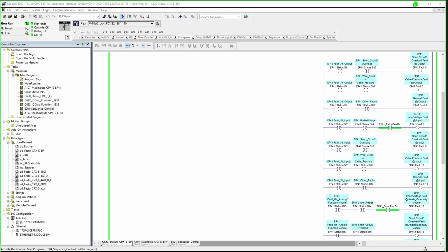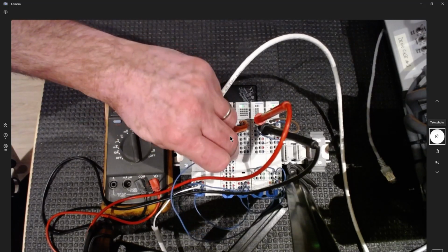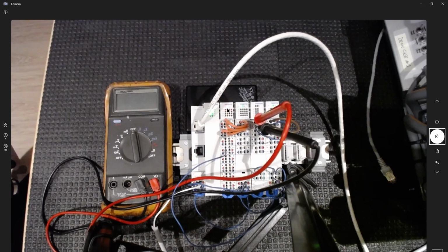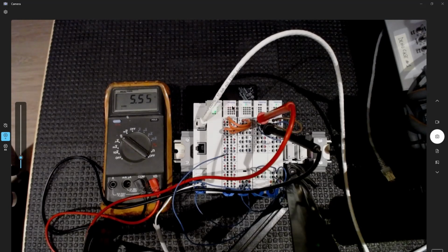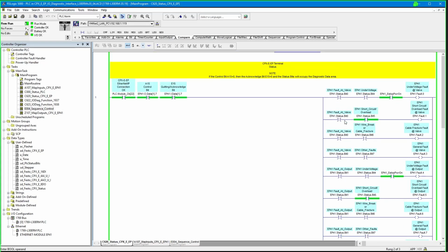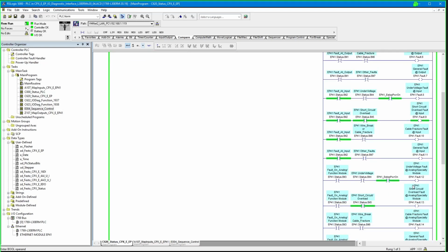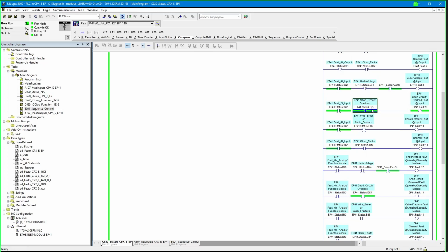What I'll do here is trigger a fault by short-circuiting module number 1. So you see here you have a red LED. It's not the best view here. Okay, so I have the red LED on here, and if I go to my PLC code, you'll see connection's okay, control bit and acknowledge are off, and therefore these are an active grouping, active fault, and we have a faulted input. It's a short circuit, so the combined fault means short circuit or overload fault at an input module. So it's very generic in nature.